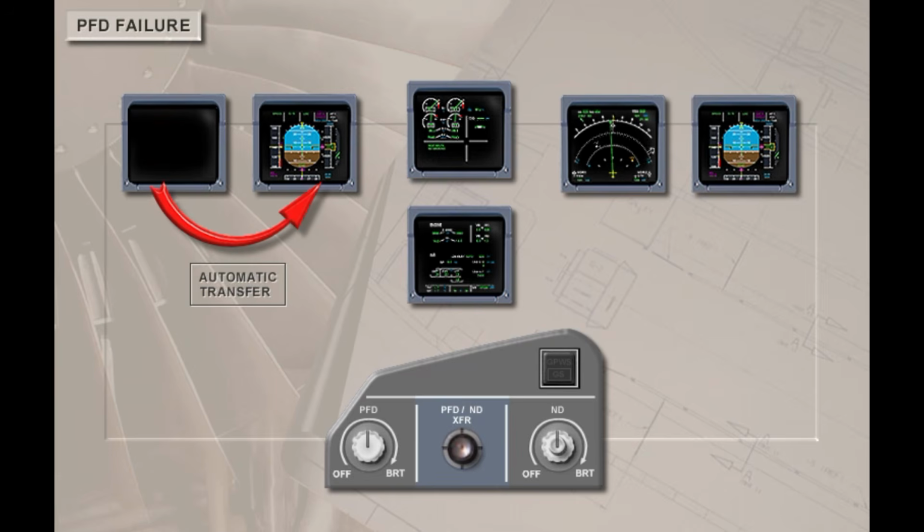The captain's PFD unit has failed and has automatically transferred to the nav display unit. Touch the PFD nav display transfer push button to view the nav display.